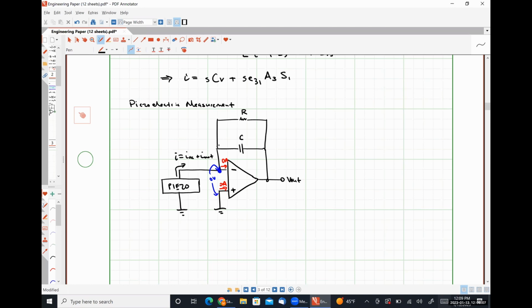Since the AC part of this current is proportional to the voltage drop across the piezo material, and the voltage drop across the piezo material is 0 because both sides are effectively grounded, this part goes away. And so we're only going to see our motional current get converted into an output signal voltage, which is awfully convenient because that's the part that is proportional to the applied stress, the applied strain, okay?